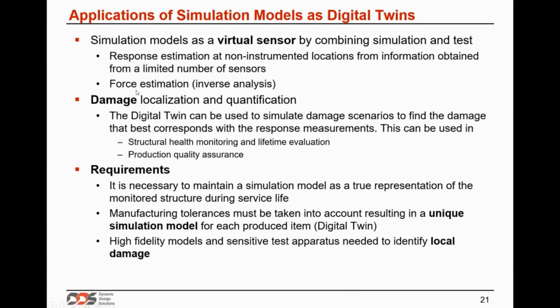Another application is force estimation. From the observation of the deformation of the structure, it is possible to estimate what the forces are. So if the monitoring reveals changes between the test data and the reference simulation data, then this information can be used to localize and quantify damage, using techniques like model updating, as I showed on previous slides.